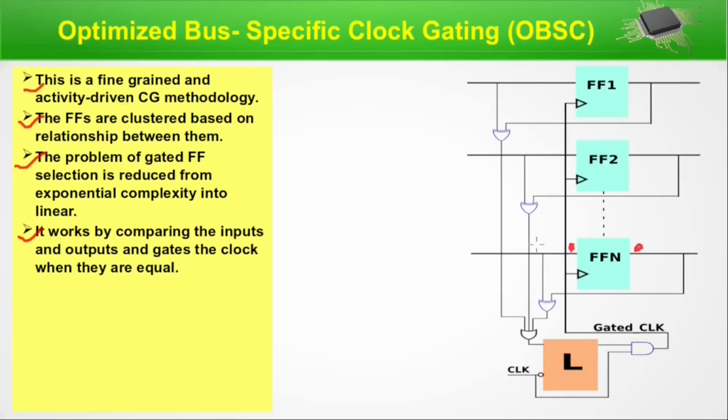We understand that. Now a new signal has come, new data, that is 1. At the output it's 0. So 1 and 0 are fed to an XOR gate, A B bar plus A bar B. So that is 1, the output of this is 1.